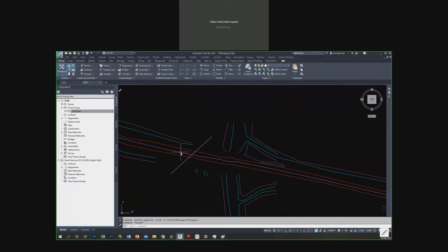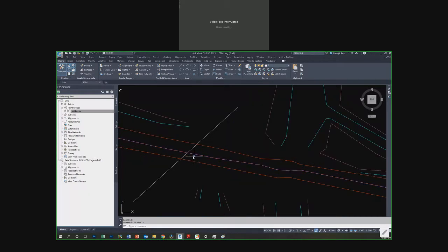And now from this break line, it might be crossing from 101 to 102, depending upon the scenario. So this particular line will have a value between 101 and 102, and the other has between 100 and 119. So at this point you will have two elevations, which is not possible physically, unless you are on a cliff or something like that, where you have same xy but two z values. So it is not possible in this road.